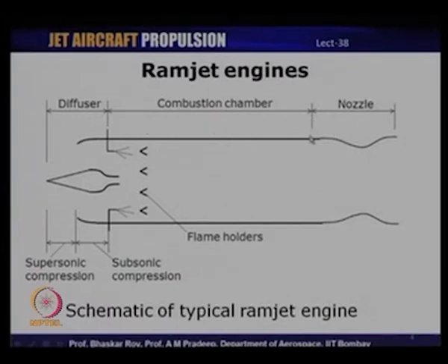So, the length of this combustion chamber will be decided by the fuel itself and the fuel particle size, the spray droplet size, because there is a certain length, residence time as it is called, required before which the fuel particles can completely ignite and combust.